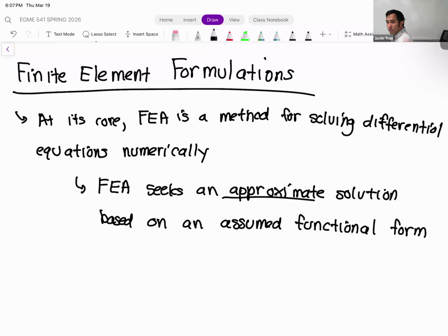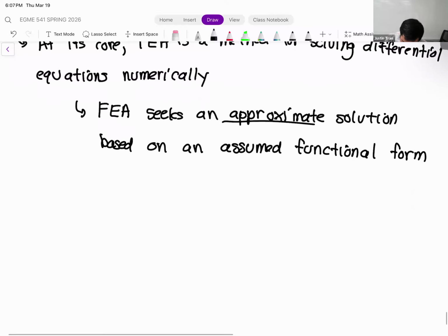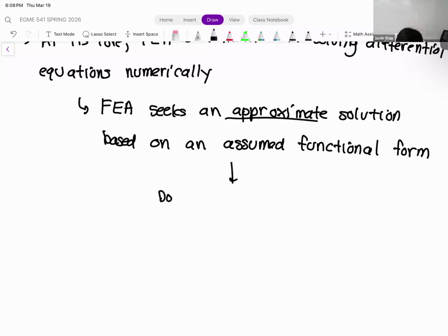Just like we did in the previous problem, when we solve for finite element solutions, we are going to assume a functional form. Usually it's going to be a polynomial, that's what works out the best. Then we work it through our weak form and solve for its solution. The biggest difference is that instead of solving for a weak form solution that's valid across the entire domain, we are instead going to break up our solution on different elements. So we do this for each element.